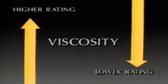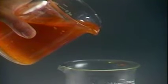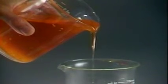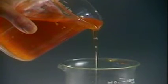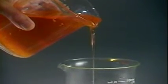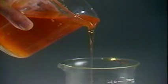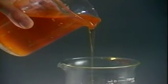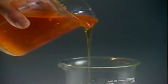Viscosity becomes a prime consideration when the temperature gets low. When the temperature drops down into the freezing range and lower, a point is reached where oil will not flow at all. This, of course, can cause serious problems in a fuel oil heating system. This frozen beaker of oil will give you a good idea of what can happen to the oil in outdoor storage tanks and supply lines in freezing weather.